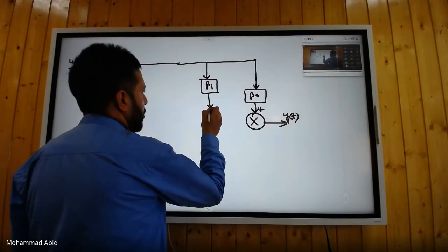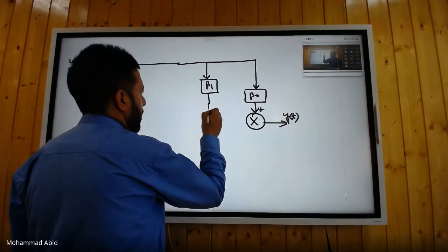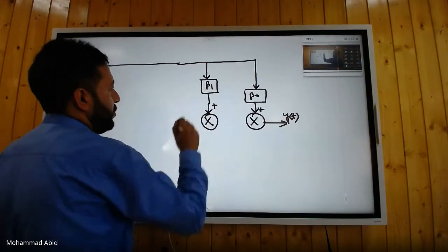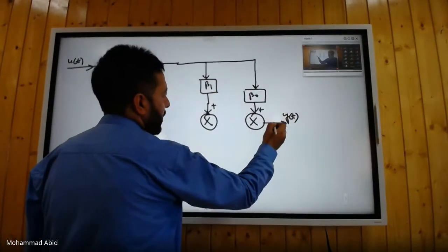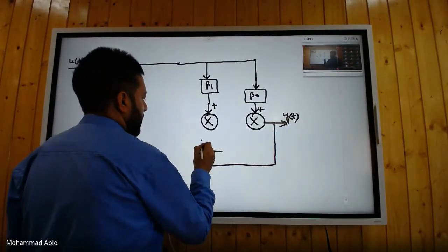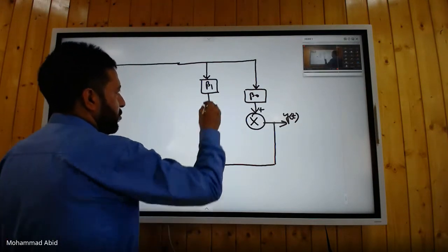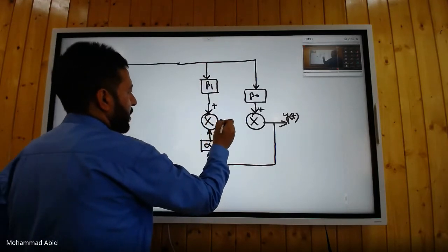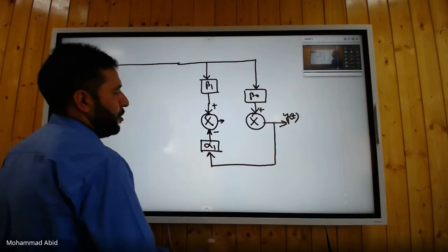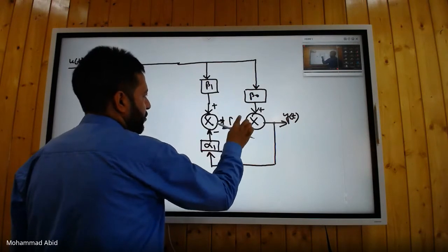So I have a summing block here, like this. This is plus. So this becomes beta 1 ut. Then I have alpha 1 yt. So it's like this. And like this. This is alpha 1. And this is minus. So this output here is beta 1 ut minus alpha 1 yt. And it's to be multiplied by 1/s. That means the integrator. The integrator will be shown like this.